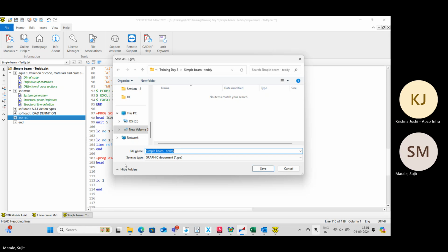If a sag happens here, the head here will change. Then you measure the pressure output, from which I calculate how much the head has changed. I used to get the change in head value, and based on that I used to say that at this time the deflection is this. The assumption was that this reference point on top of my tank is at a constant level. It was shown on the screen.